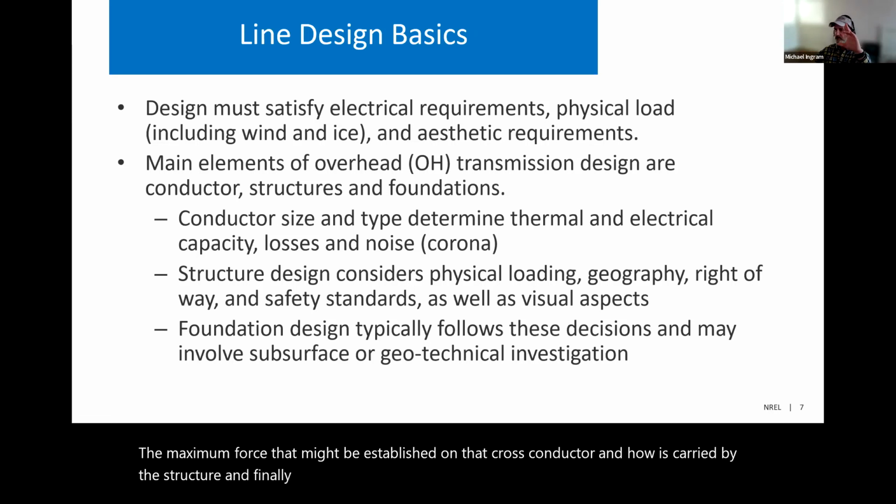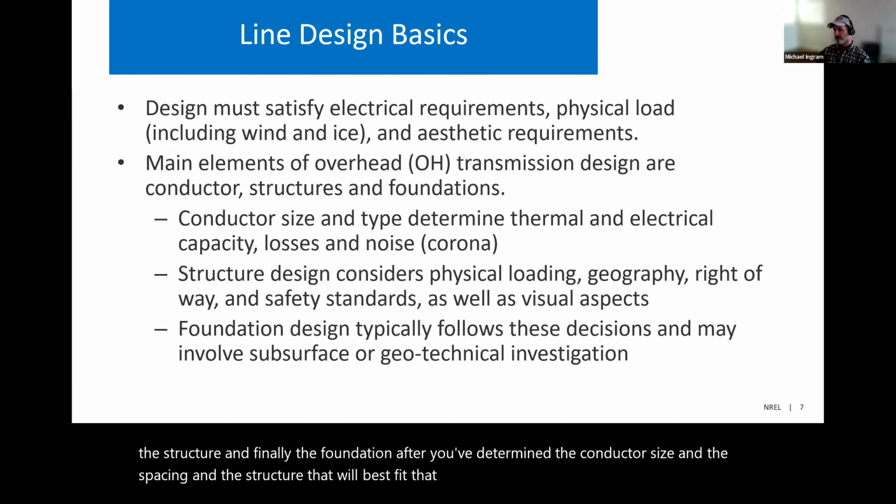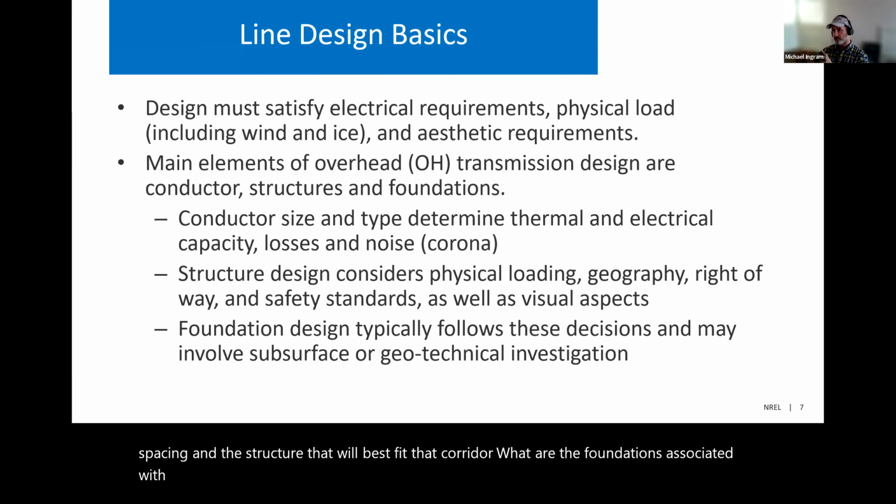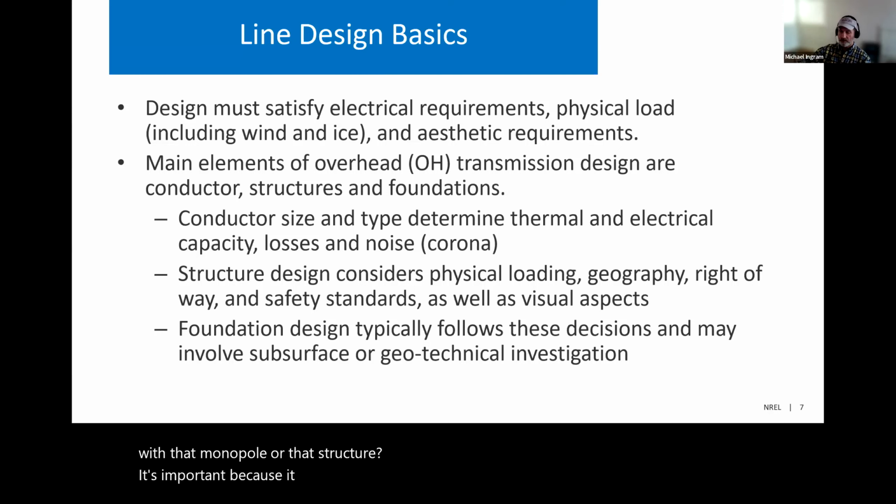And finally, the foundation. After you determine the conductor size and the spacing and the structure that will best fit that corridor, what are the foundations associated with that monopole or that structure? That's important because it may require additional survey to understand how well that foundation needs to be designed.